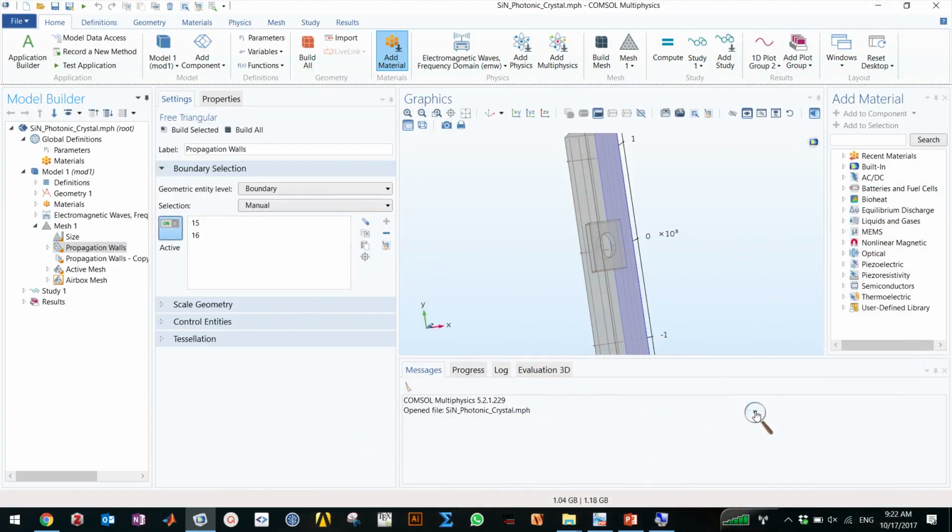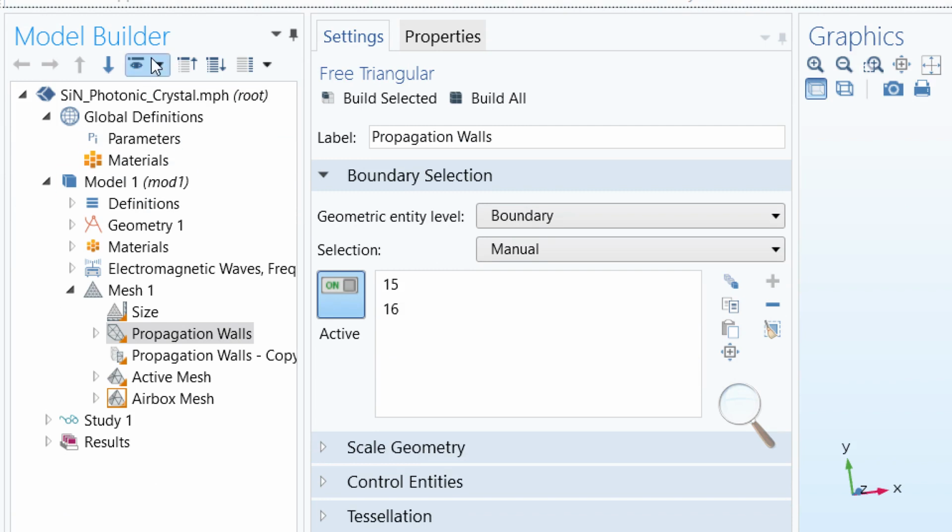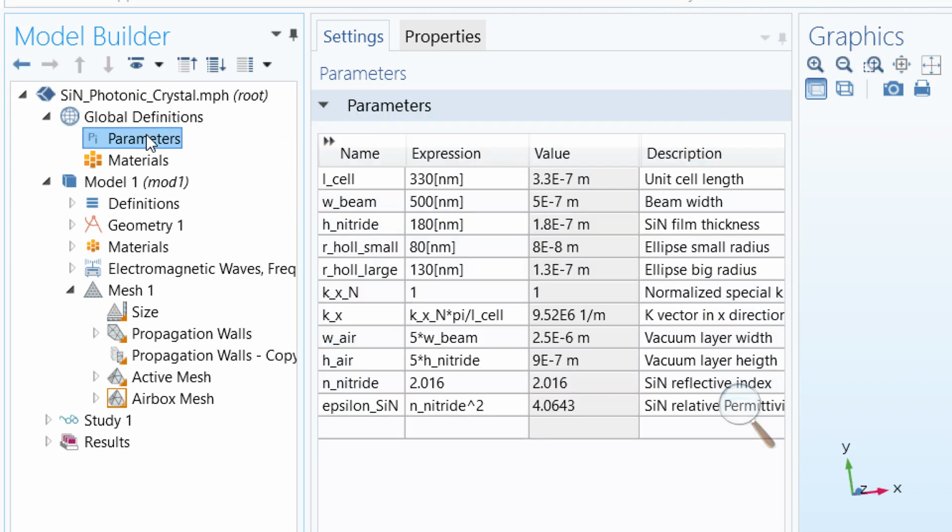Why not PML or scattering boundary condition? It doesn't work with the Floquet condition. It doesn't exist. It's a Floquet condition. So the perfect electric conductor boundary condition is now where we put the periodic boundary condition? No, it's different. We just put PEC like in the Z direction around it, not at the faces that are Floquet. Yeah, we'll get to that.